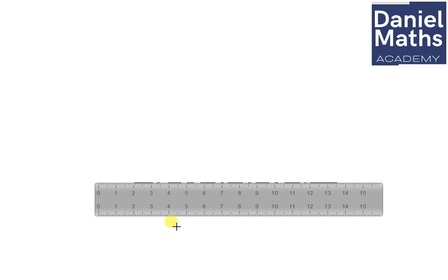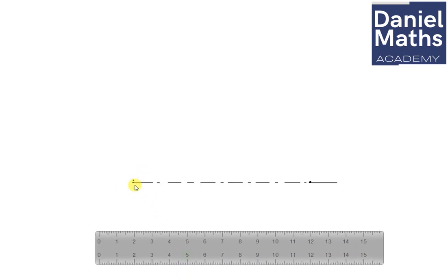So I'm going to stop at this point. Now I have to note this point. I'm noting this point as my point A, and I also have this other point noted. So this is my point A, and this is my point B. Take note that what we have here is 2 to 12, that is 10 centimeter, which is equivalent to 100 millimeter.